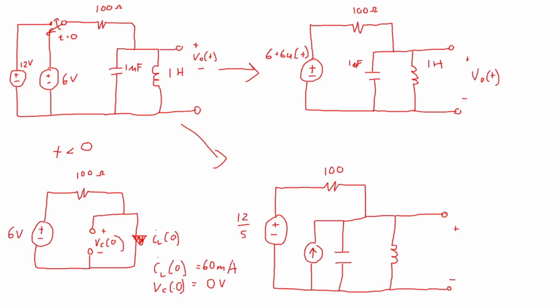And so C times VC is a 0 ampere. I guess it would be microamperes when we multiply volts by microfarads. But 0 microfarad volts are 0 microamps or 0 amps. And so the source that the capacitor produces as its initial condition has a value of 0.